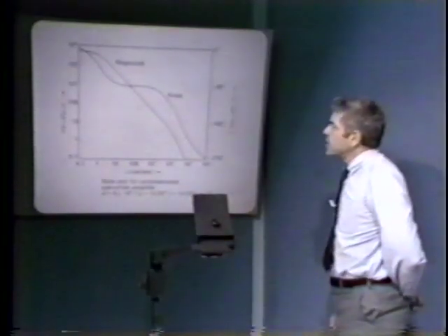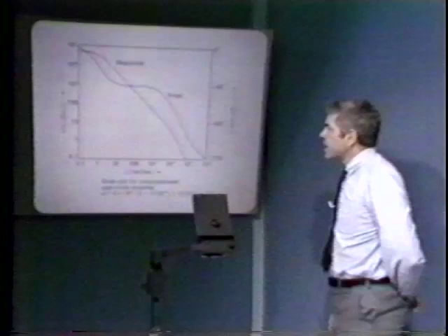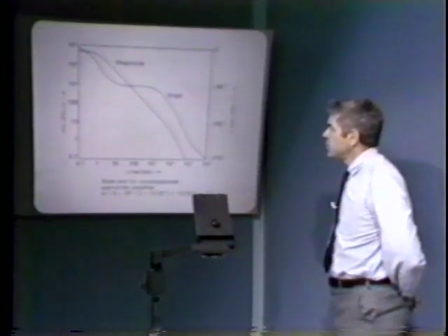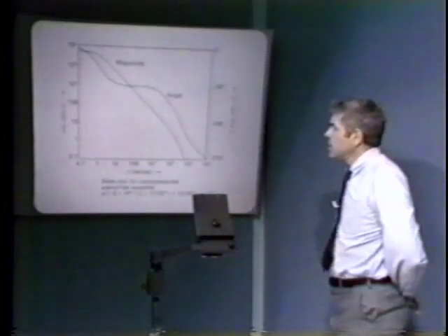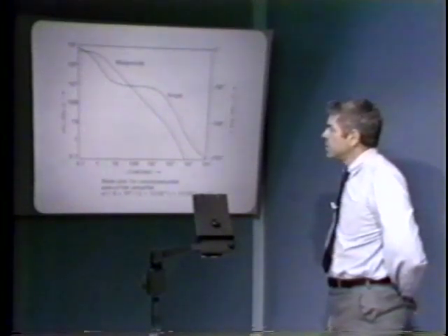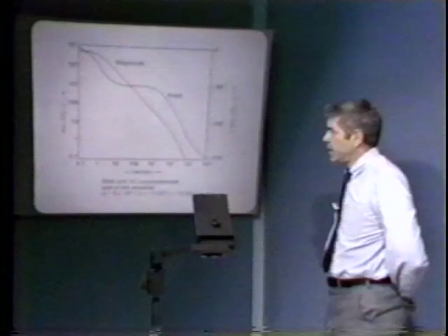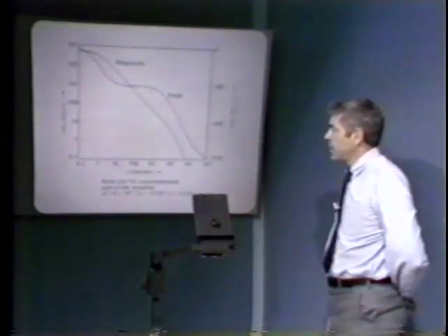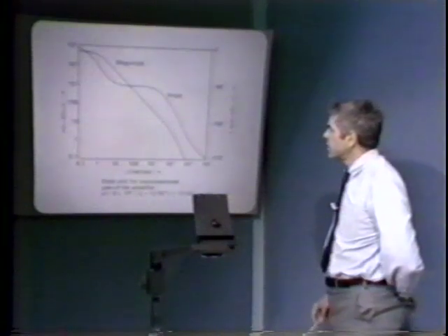This is, of course, the gain, or the AF plot, the negative of the loop transmission plotted in Bode plot coordinates that we get for our uncompensated gain of 10 amplifier. We combine the A of S associated with the amplifier with the factor of a 10th that equals F.